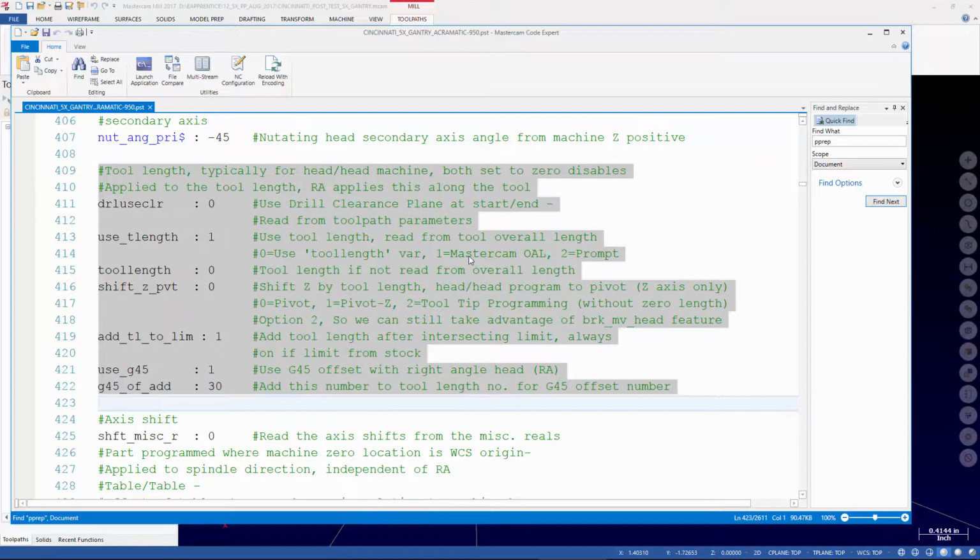And with this style of machine, the XYZ point that you see is always the pivot point of the machine. Even if we're doing what would normally be 3-axis work, the Z is always offset by the length of the tool. And that is so that we can program with these known tool lengths, and we can drive the machine in a 5-axis mode, and the XYZ code that we give the machine is what makes it cut the part.